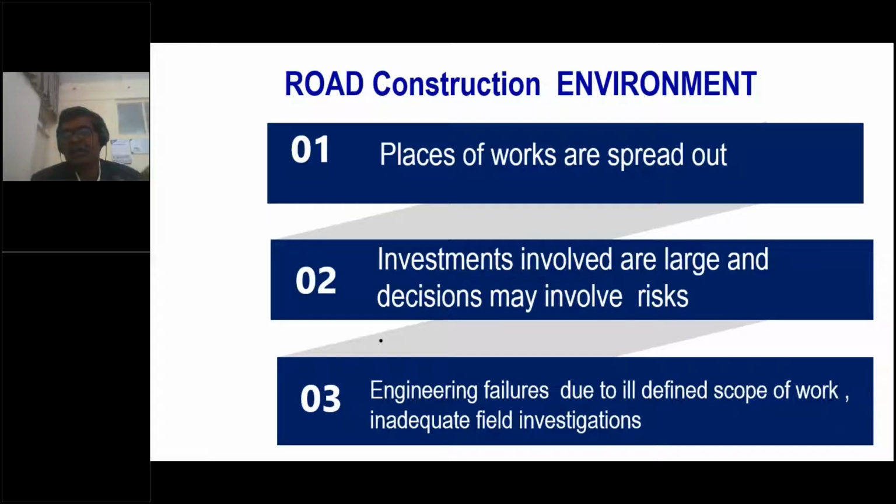So it has so much implication. I cannot continue with my execution because the difference between 2 and 5 has a lot of financial implications. So I am forced to stop my execution in spite of mobilizing my resources to the site. These things do happen because we cannot test the entire population. Let's say I'm preparing a 100 kilometer DPR. It is humanly impossible. So we take representative samples every 1 kilometer. In between 1 kilometer, the strata may change, the properties may change.